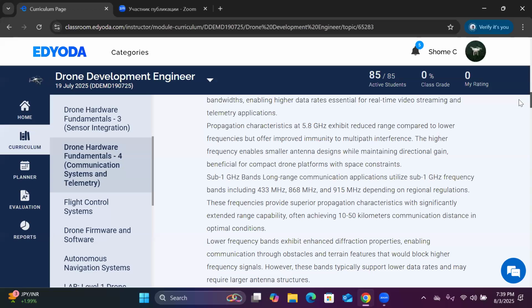Okay, so depending on the regional regulations, if you use the dual band GPS receiver, or the dual band modules, there the frequency will be restricted to 2 frequency bands. If we use the tri-band module, there the frequency will be restricted to 3 frequency bands. So for safer side, we can take the tri-band modules, so we don't need to change the design. For the tri-band modules, the antenna supporting will be tri-band. So with the tri-band antenna, if we go for the dual band, automatically it will support the dual band.